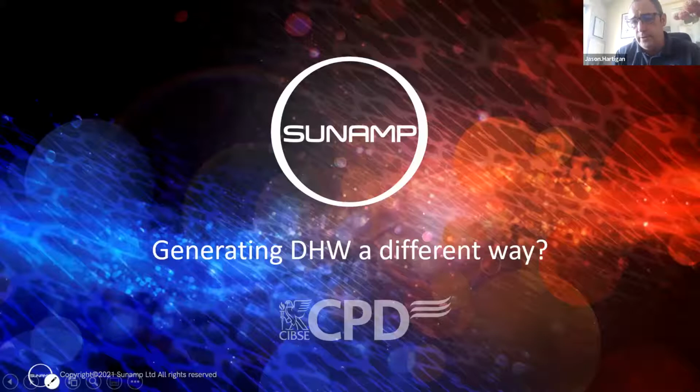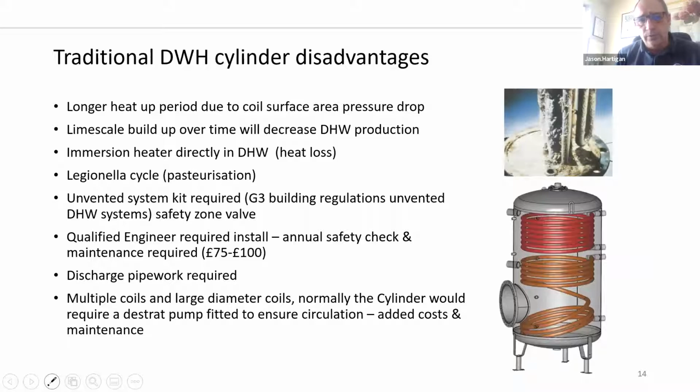So what if we can generate domestic hot water a completely different way? What are the challenges? If we look at traditional domestic hot water cylinders, generally we'll have a coil in there. You'll have an immersion heater, so you'll have the boss of the immersion heater sticking out the side of the cylinder, and generally it would be in the water to heat that up.